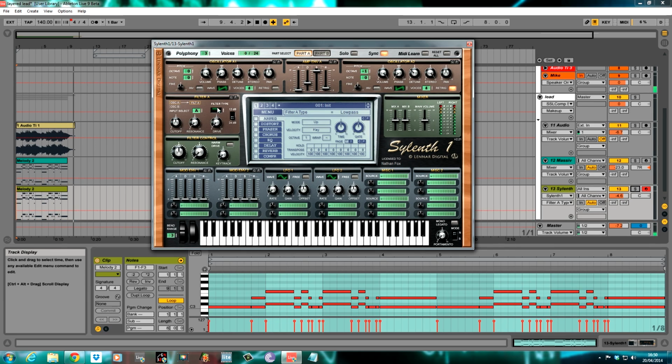Push it up till you get the low pass filter showing. So input select is A. Push the cutoff round to about 607 Hz, keep the resonance where it is and the drive where it is, and keep it on 24 dB per octave low pass filter. Okay, that is it for part A for the minute.